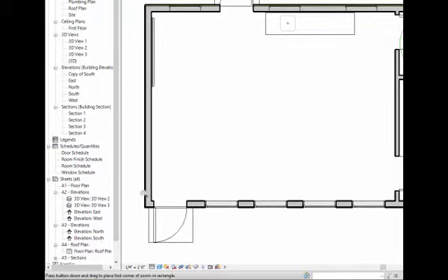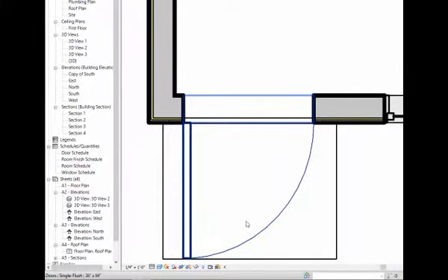Okay, as you look at the drawing and we think about dimensions, there's the question of what we dimension to. Do you dimension to the inside face, the outside face, the core face? There are a lot of choices available, and the one that typically makes the most sense is to dimension to the core faces. The reason is that's the point the carpenter will typically lay down the wall with. They'll put the face of the stud at a specific location, so it makes sense to give them information that helps them place that accurately.